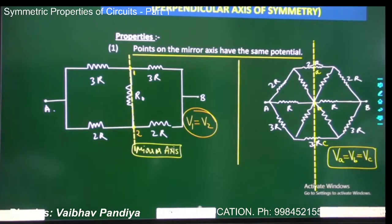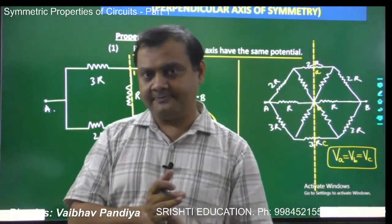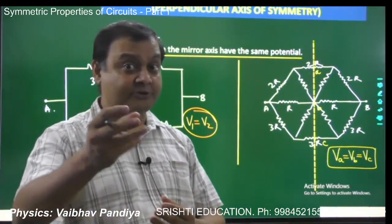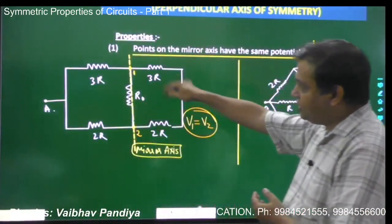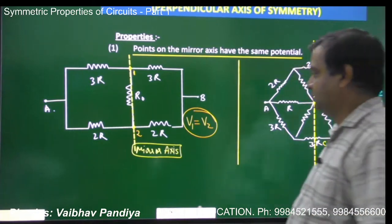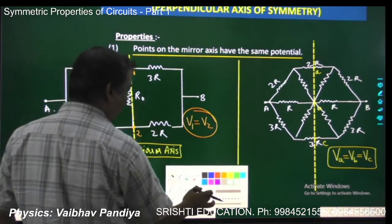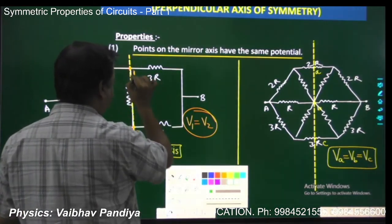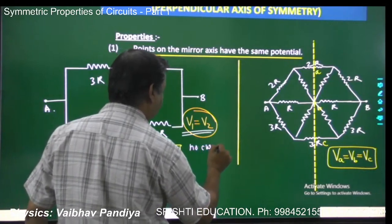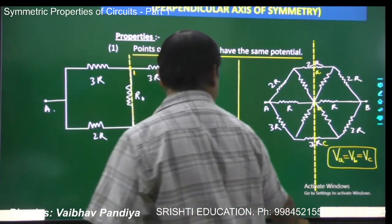And what can be concluded by this property? So we know the basics of electricity. For the flow of current, there must be a potential difference, there must be some voltage. If the 2 points are equipotential, if the 2 points are at the same potential, no current will flow between them. So we can say there will be no current through R0. In this branch, there will be no current, because they are at the same potential. So you can conclude no current in R0.